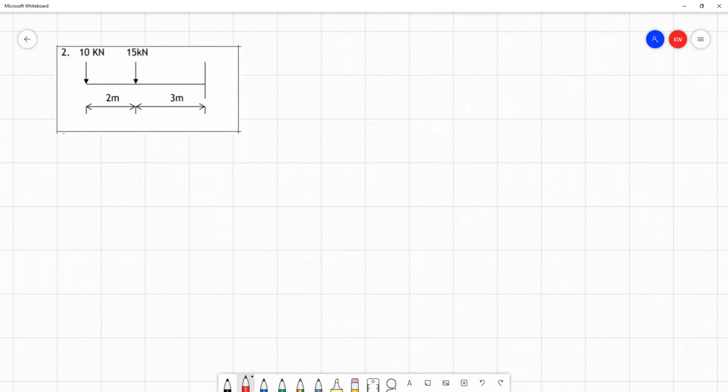If we look at the beam here, we'll see it's supported at only one point, this right-hand side, and this is a fixed support that's going to provide reactive forces to any horizontal or vertical forces and to any moments that are applied relative to this point. So we'll label this point A so we can get an understanding of what's going on here. We'll imagine that there could be vertical reactive forces, which I'll call VA, could be called RA, depending on the names. There could be horizontal reactive forces, HA, and there could be a moment, and we'll find out which of these actually exist.